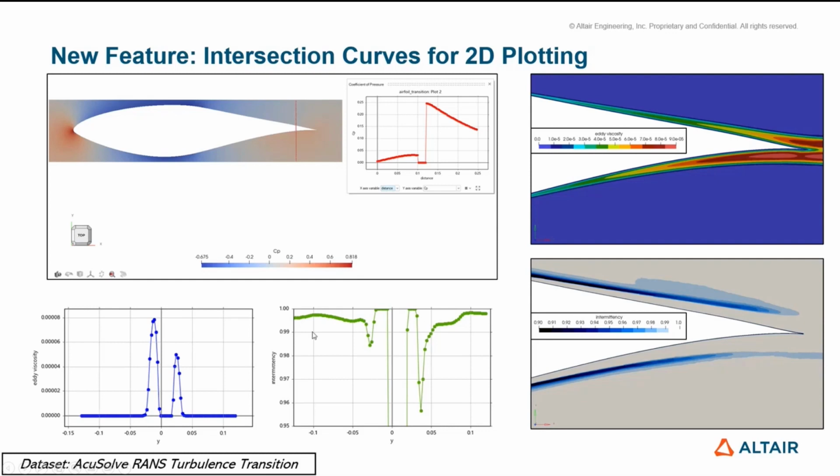with my intermittency moving towards 1, I can see that I do have an increased eddy viscosity at that location. And then that's backed up just by a qualitative contour to show that, okay, yep, there is this shear layer happening right near the foil. And our intermittency goes to 1, indicating that the flow is fully turbulent at those locations. And that, of course, matches up with the eddy viscosity that we plot in the wake of the foil.